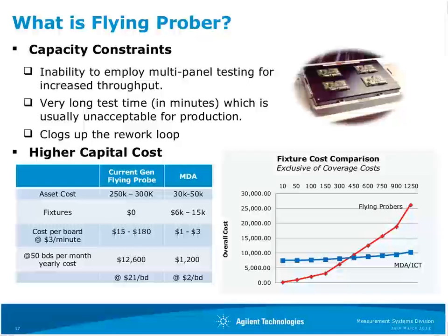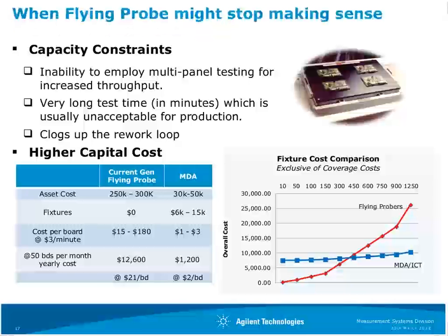Very often, the engineering effort and time is not taken into consideration in a low volume environment. But just consider when you're under pressure to take a small batch of 5 or 10 boards through production and into final test stage. If you examine a case of a typical 1,000-node board, the time for this at flying probe would be in the region of 15 minutes for a standard short, open, and analog test. And considering there may be some rework to do, maybe some minor adjustments to the test program during production, then typically this will take around 4 to 6 hours to complete those 5 or 10 boards.